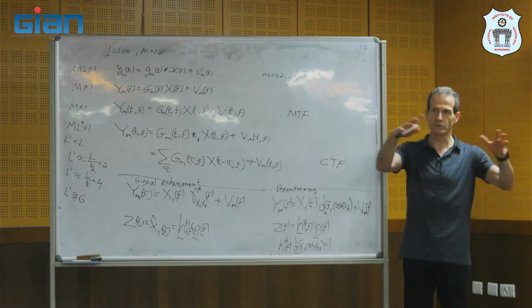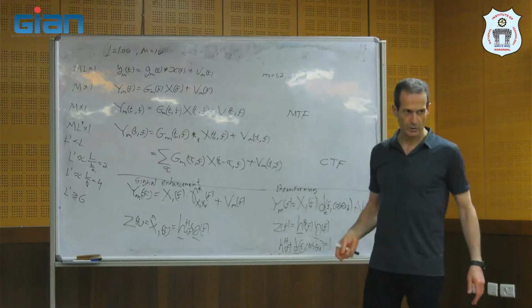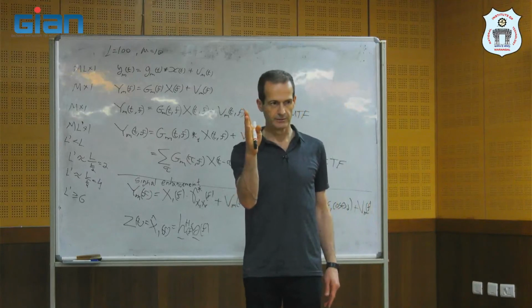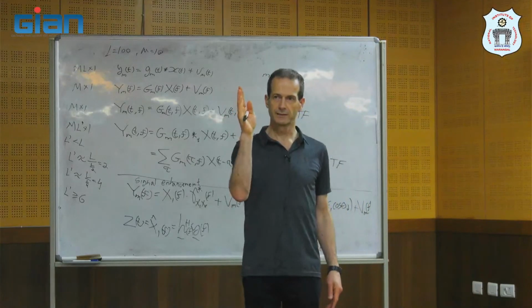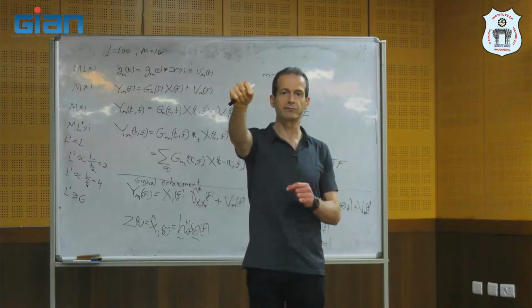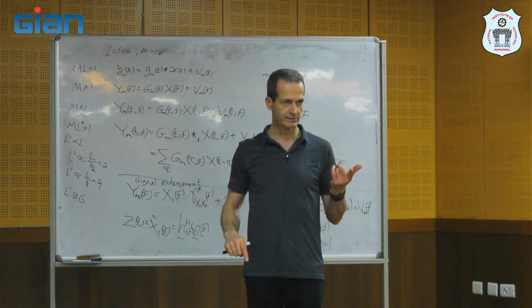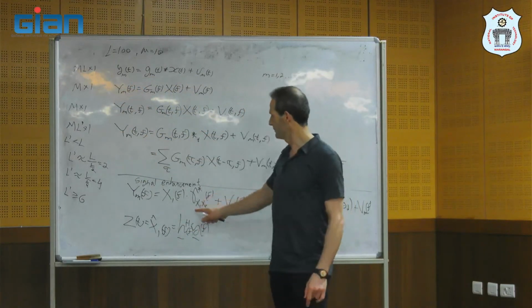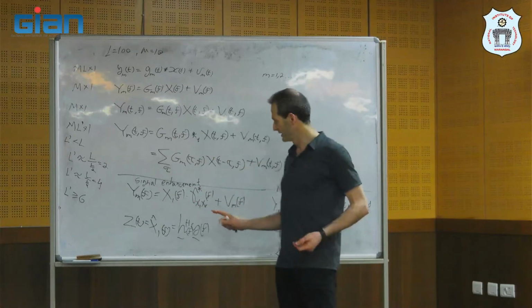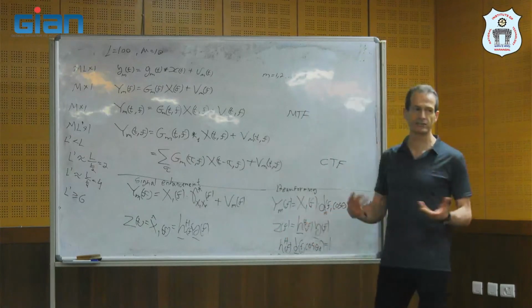I'm talking about sources in the room, but it's also possible with radar or something like that. So if the direct path, the direction towards the desired source and the interference, is the same, because they are in different positions, the pattern of reflections is different. And here we can distinguish between both of them, and we can separate them. Here with a beamformer, we cannot, because we don't take any reflections into account.